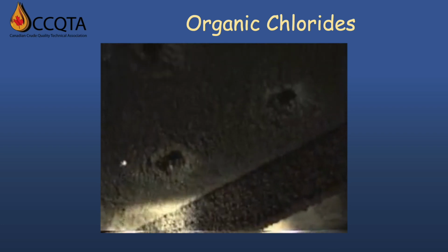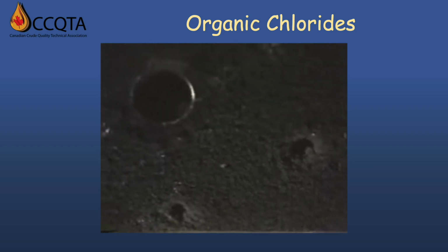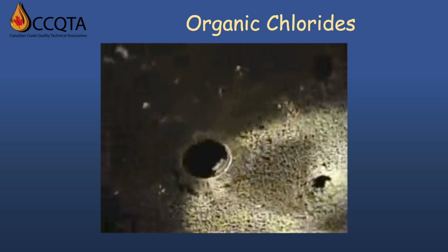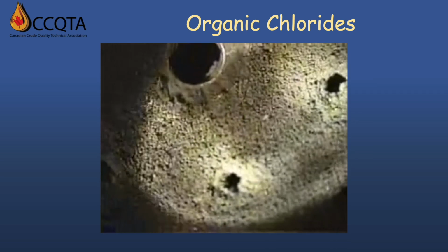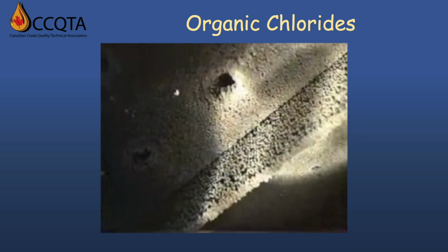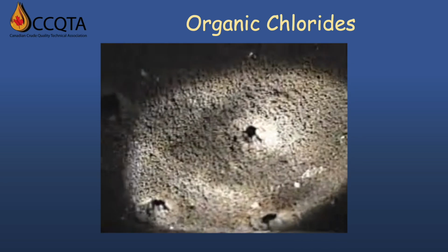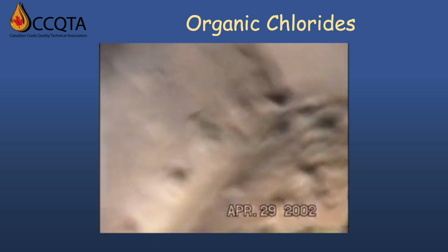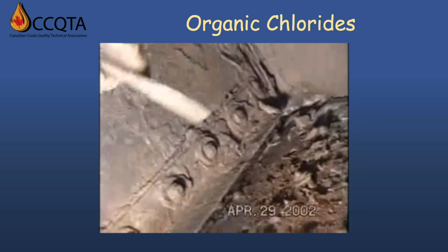As previously discussed within the CCQTA's phosphorus and crude project, this particular additive has been connected to phosphorus-related fouling in the refinery crude towers, specifically in the jet and diesel draw areas. This fouling material reduced the diameter of the tray holes, limiting throughput, allowing trays to flood. This is another example of phosphorus-related fouling being scraped off the walls of the tower.